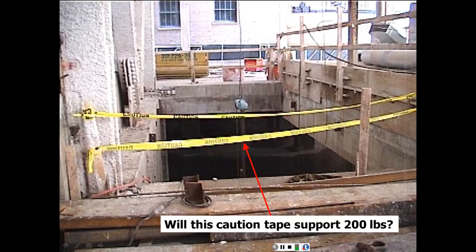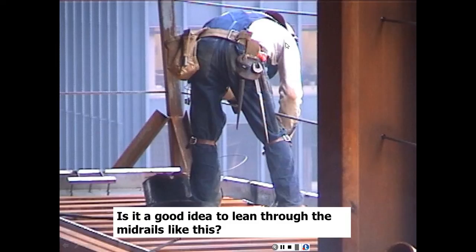This one seems to be okay, however. Although it's missing the toe board, we have a mid rail and we have a top rail. Now, although here we have the lines and everything, they're not flagged, but now he's working outside of that line, so it defeats the purpose, as if the line doesn't exist. So definitely this is not a good idea.